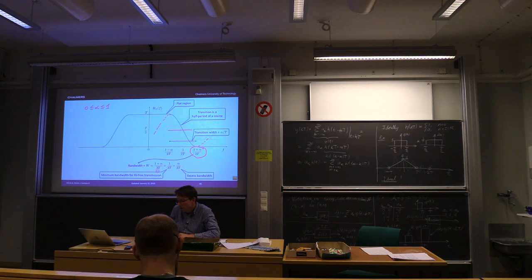And we can split that out to be 1 over 2T plus alpha over 2T. And if we think about that a little bit, we continue to write this. This is 1/2 times Rs plus 1/2 times Rs times alpha, Rs being the symbol rate. Okay.